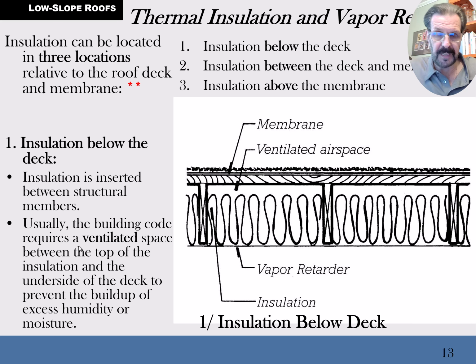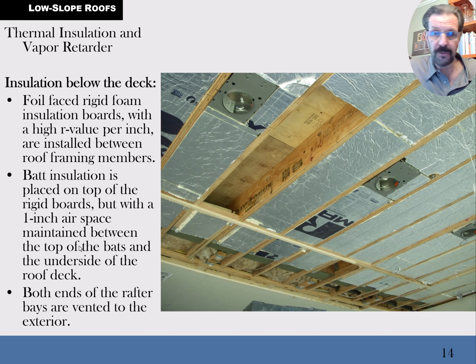But that's when you can see the insulation up on the deck in any fashion, unless it's spray foam. Then you've got to ventilate in between each of those areas. That means you have to have a vented attic no matter what. Okay, so this is showing a picture of what you might expect.